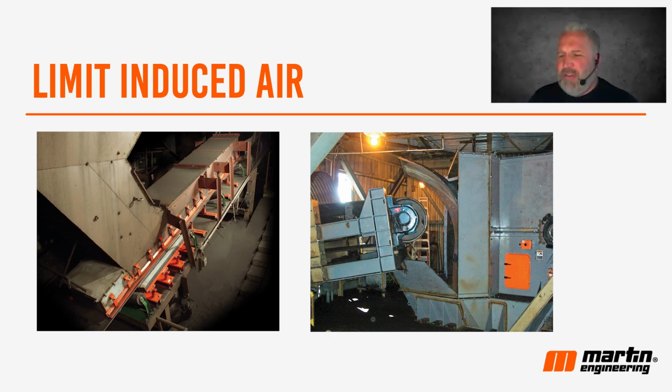You also want to try to, if you can, reduce or limit what we call induced air. As material comes off a head pulley, that material expands, and as it expands, it has to surround itself with a volume of air. It's not in a vacuum, so it pulls air in between the particles. As that material and air then land on a receiving belt, the material settles and pushes that air out. That's called induced air, and it's problematic.